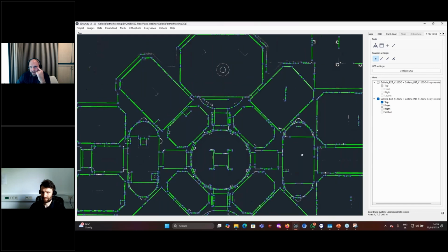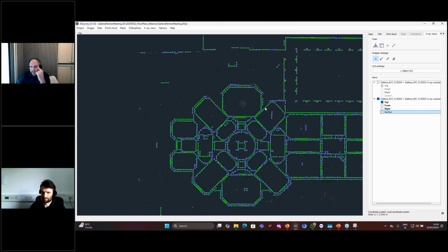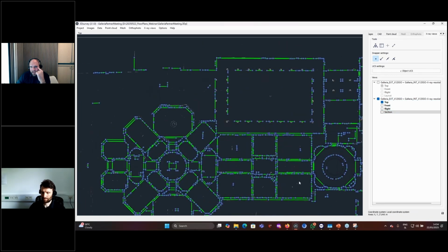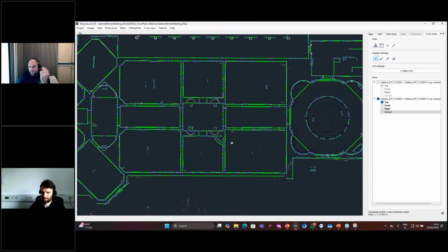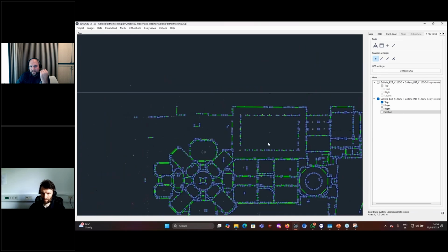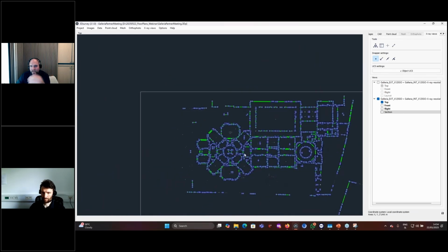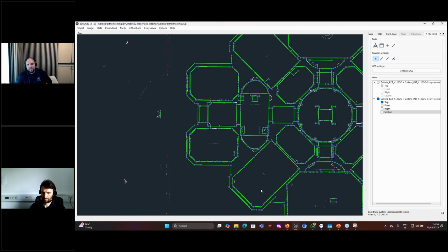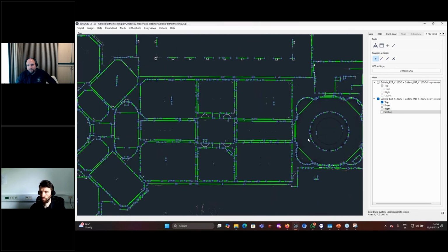So in this example, you don't really need to worry so much about creating sections. You can just create a top view, and in this case you will also get line detection to work nicely on the top views. This works well if you are doing floor plans for some big store where it will be cleared out for scanning. In that case, it can save you a lot of time because it even works greatly on this kind of clear example.